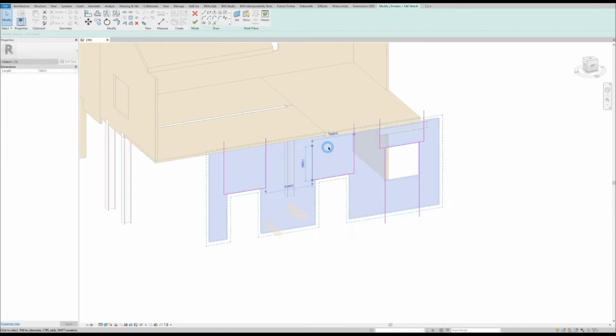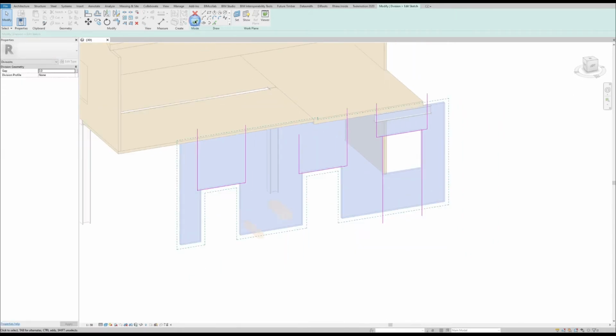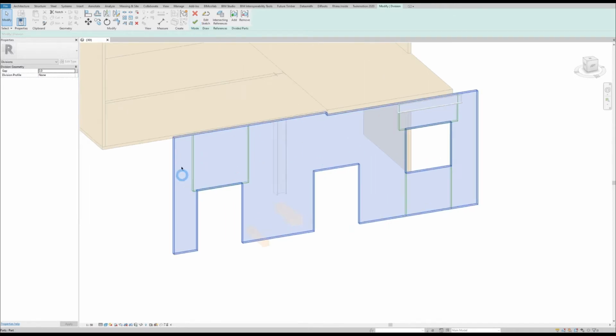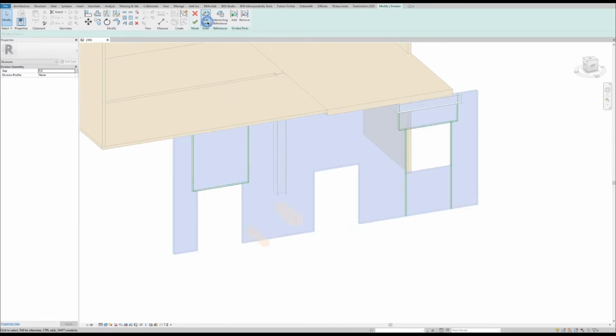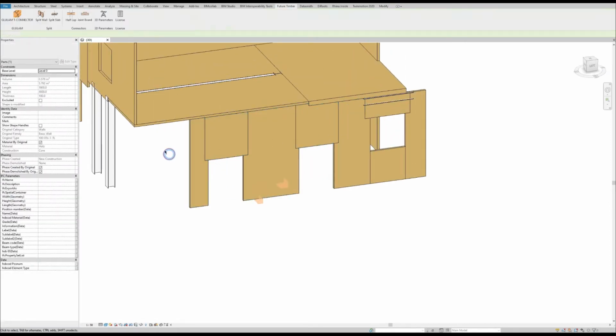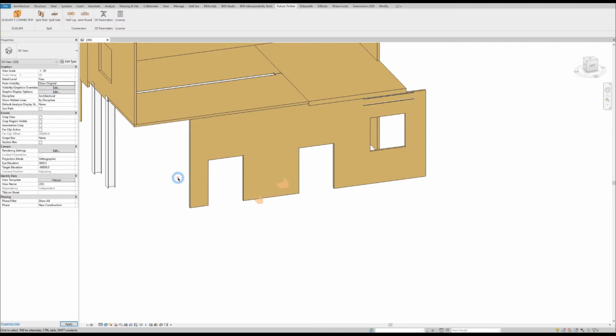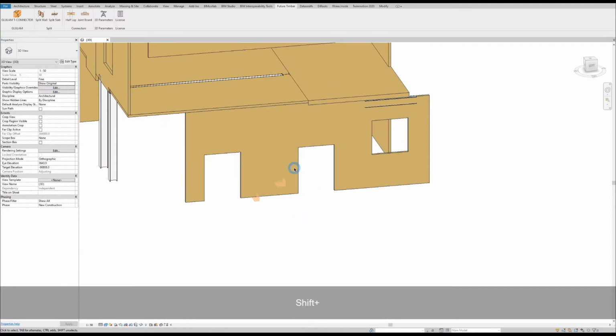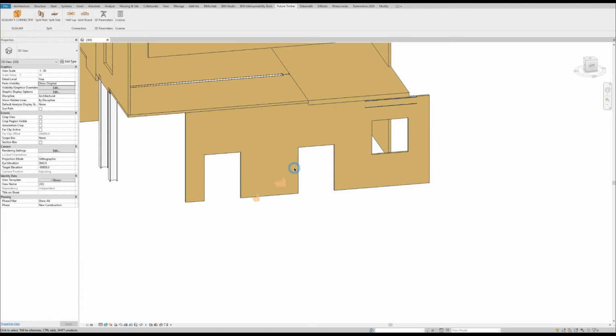So for example, if I bring that back down, we can see it's not breaking that line there. If I press OK here, it doesn't split. We can see sort of the split line there. But if I edit the sketch again, I can then quickly just bring that up, and we can see that's done there. So now we have these little subcomponents of the original. So the interesting thing about this is that the subcomponents are hosted within the original element, and whatever modification is done to the original element won't be lost on the parts, but the parts won't automatically adjust, of course.